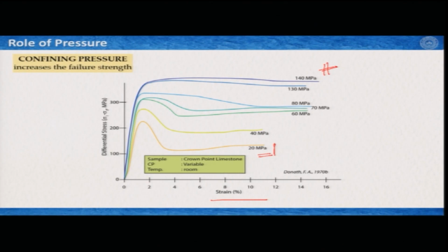If we look at all these stress versus strain curves at different confining pressures, where the temperature and the strain rate are kept constant, we see that it has an extremely variable behavior under stress. At low confining pressure, it goes to its elastic limit, and then it weakens, what we call strain weakening, which we learnt in the last lecture. Then it does a little bit of strain hardening and flows steadily. Whereas at 140 megapascals, it reaches its yield strength somewhere here, and then it flows steadily.